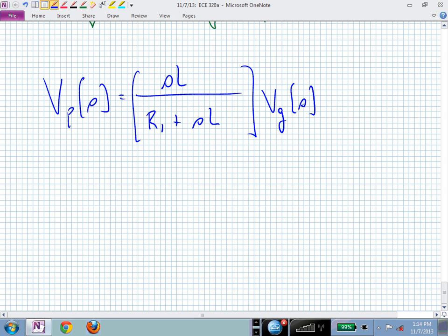Before I go any further, though, what can you tell me about this circuit? Can you tell me the order of this circuit? So this little transfer function, what's the order of this little transfer function? The order depends on the degree of the denominator polynomial, doesn't it? What's the highest power of S in the denominator? That's 1, isn't it? So this is first order. This is a first order circuit. The description, though, we haven't normalized the constant to be 1, so it's not in time constant form. We haven't normalized S to have a monic coefficient of 1, so it's not pole zero form. This is kind of nothing in terms of our forms.